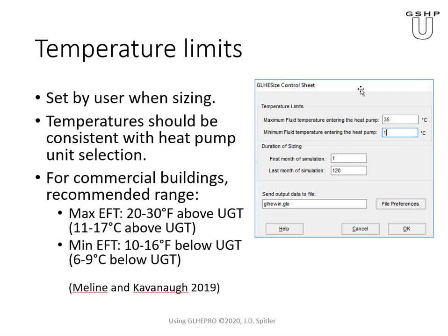So the temperature limits are set by the user when sizing. They should in general be consistent with the heat pump unit selection. So when you select a heat pump for a zone, say for maximum cooling, you have a maximum cooling load. In general, I think your heat pump should have enough capacity to meet the zone load when you're at this maximum entering fluid temperature. The maximum entering fluid temperature and the maximum load for any zone may not coincide, so there's some margin of safety by making sure you can meet the capacity at the maximum temperature. But in general, that's what I'd recommend.